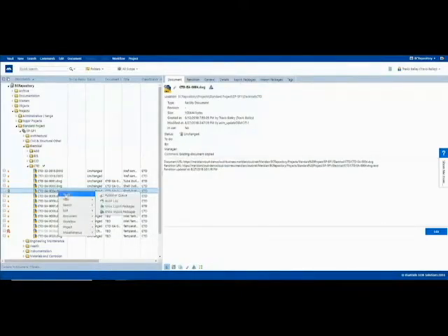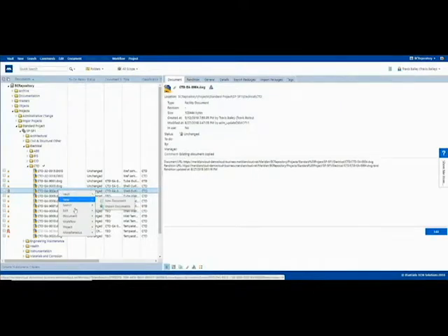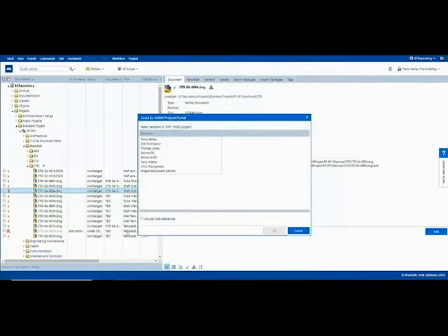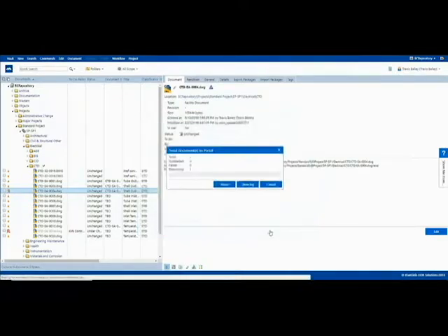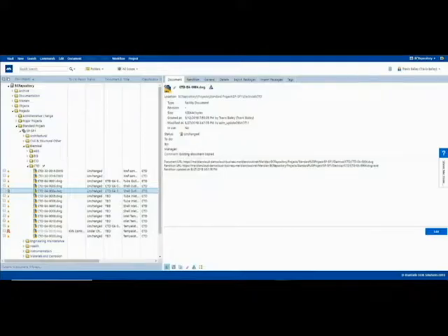With our new project copy, we're going to send it to the contractor in the portal. So we simply right click, workflow, send to portal. And based on our Meridian portal project, we have our recipients. We're going to select Contractor, include CAD references if there are any. Hit OK. And the drawing and that data went to the portal.